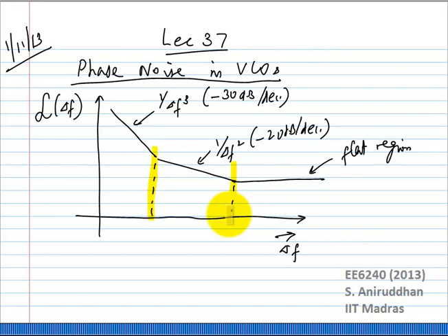If you look at Leeson's noise model, what the LTI noise theory does is it empirically postulates the presence of each one of these for any oscillator, and it uses an empirical factor to try to account for some of the noise increases from what you would normally measure.